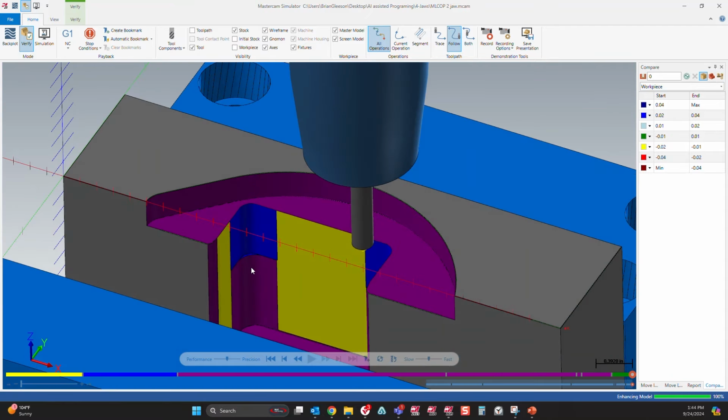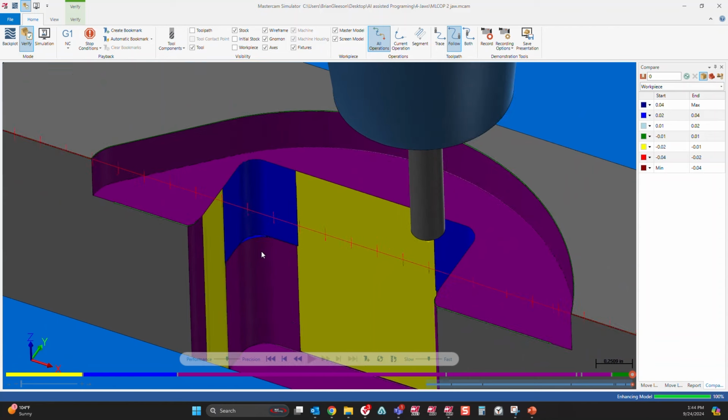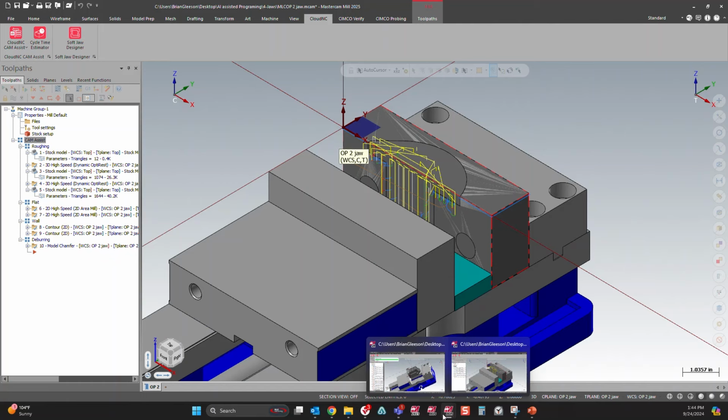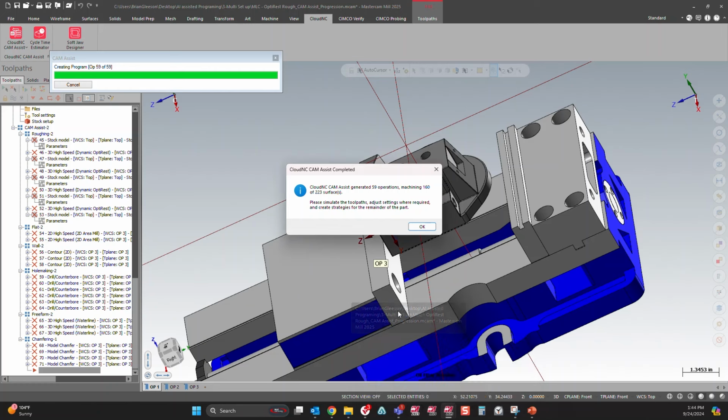Some of these corners, the tool library didn't have anything relieved that long, that deep. So I could come back and modify that tool path and make sure it gets that deep, or I can put that part in there. It is angled, so it might not be hitting there anyways. We'll give our next part a look.